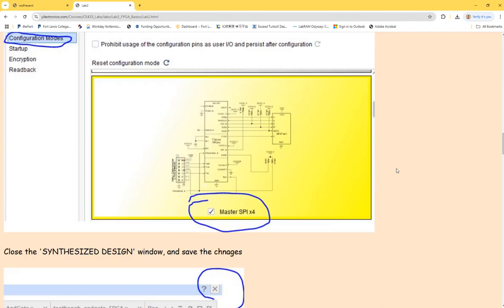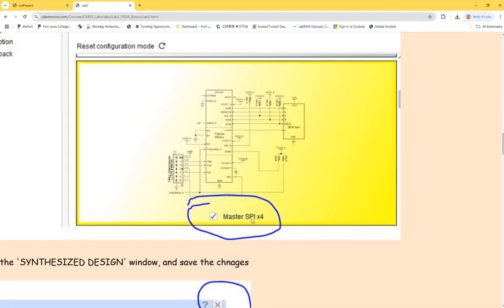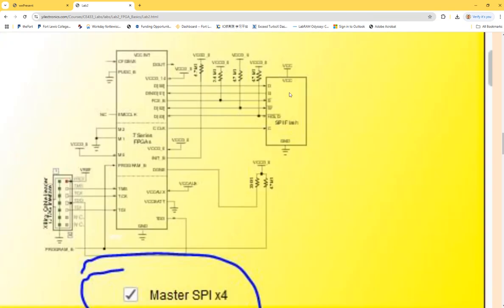And eventually you set up this guy. This configuration is important. Okay? So this one defines the communication between the memory chip, which is SPI. So SPI has 4 ports. Did the microcontroller cover SPI? Not yet. Okay, so we will cover this later this semester about the protocol. So there's a chip. I think this guy, SPI flash. It's onboard memory. If you flip the board, you can see it's at the bottom. On the bottom layer, there's a little chip, black square, which is the memory file.